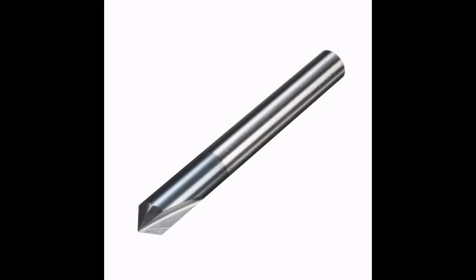And so it's designed to cut chamfers, which are angles, and our particular application uses a 90-degree included angle chamfer mill, which makes an equal height and width chamfer at 45 degrees as it profiles along. They do have a small amount of side flute, but they're primarily designed just to cut on the angled portion of what you see on the image there. We are going to be using this chamfer mill as another application instead of a spot drill to spot drill the hole locations on this Titan part.